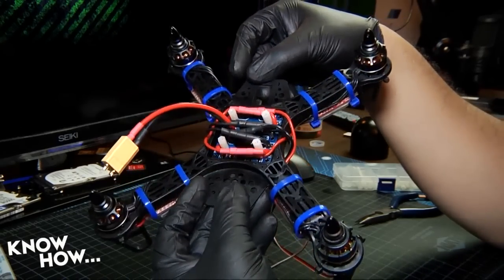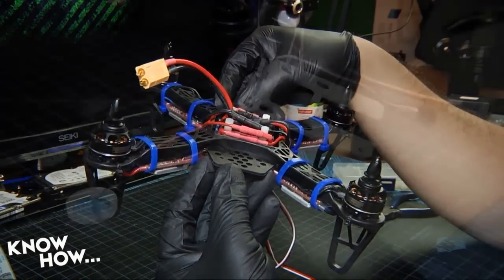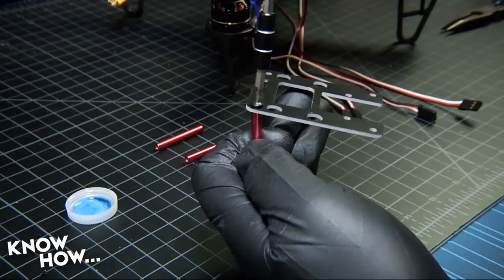Take special care to make sure that none of the metal from the bullet connectors is showing in order to prevent shorts when we power up. Now let's assemble the base of our long frame extension kit.